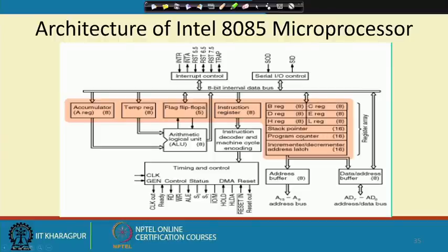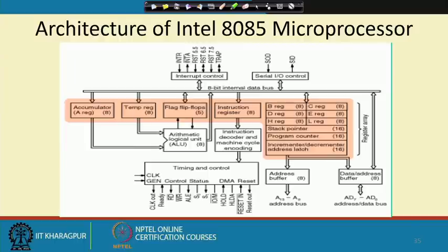As a result, the next time the processor goes into the instruction fetch cycle, this 0 value will be put through the address buffer to the address bus. The memory sees it as if the processor is now trying to access memory location 0. So if your system initialization routine starts from address 0, then the system will get initialized. That is the special thing. When this reset in bar pin is activated, the program counter value becomes 0.